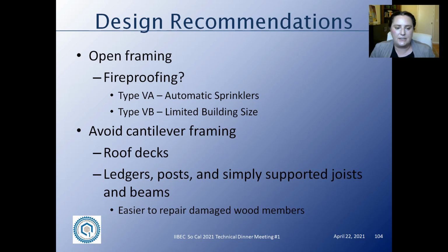So I'd recommend designing your framing to be ledgers or post and beam, simply supported over cantilever, just to assume that at some point you're going to have to do repairs on these wood members because of dry rot or termite decay or something, and it's going to be far easier to repair damaged wood members.